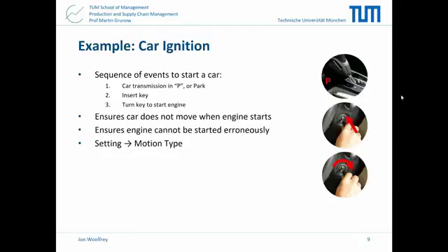So Shigeo Shingo would call this a setting or motion type poka-yoke device because it constrains the sequence of actions. And it also has a 100% inspection rate. So every time you start the car, you have to follow this sequence. Usually it works 100% of the time. And it's also low cost because it's built into the design itself.